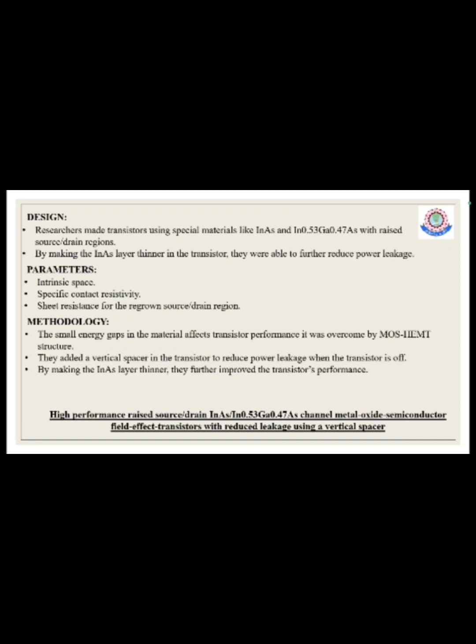They made two different samples, A and B. A has an 8 nanometer spacer and B has a 3 nanometer spacer. By observing these two, they found that the 8 nanometer spacer in sample A significantly reduced the total power leakage when the transistor is not used, compared to the 3 nanometer spacer in sample B. They said the spacer also helps to control the transistor better, and by making the indium arsenide layer thinner, they further improve the transistor performance.